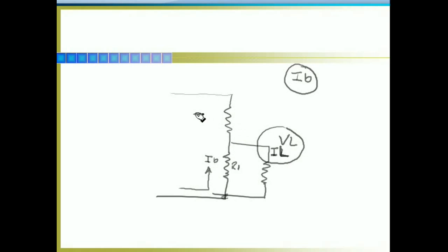The current going through your next resistor is going to be your bleed current plus your load current. And then you can calculate the resistance on that guy. Of course, you're going to want to know your total voltage. Once you calculate all that, you'll know what your voltage source has got to be able to produce as far as current goes, or what current it's got to support. And Chapter 7 is pretty much as easy as that.